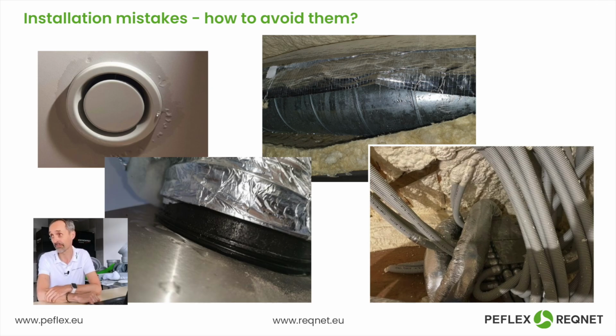A few examples, starting with this first one, which is an exhaust air diffuser, probably in a kitchen or bathroom. On the other side, there's nothing, no insulation, none of that, so the air in the pipes, meaning the water in that air, condensed and returned to this point, which means it flooded our supply air point. This is an issue related specifically to the tightness of the connection.